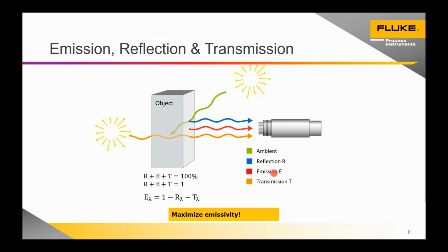Emissivity is a standard parameter. We're also able to tell the sensor what the transmission factor is, and that's not necessarily the transmission of the object. In an application, if we consider transmission, we often need to avoid that. We don't necessarily want to measure what's behind here.